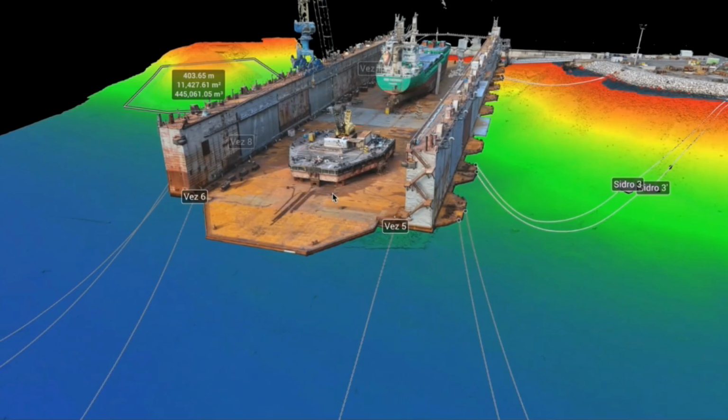And then on this side, you also have the problem with corrosion, but also some floating currents that may destroy the chain. And it is important to understand the level when you do the photogrammetry, what happened, and can you make a time shift inspection on this side to see, because the chain is as strong as its weakest link. So you need to check this weakest link and what is happening with it through the time shift series.